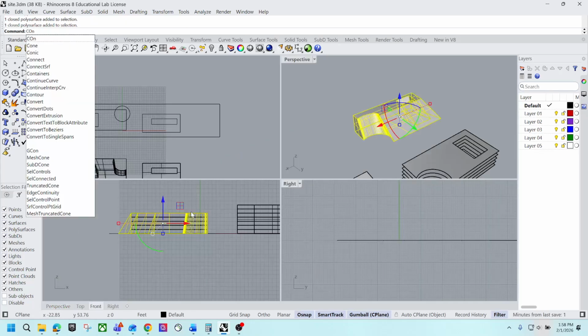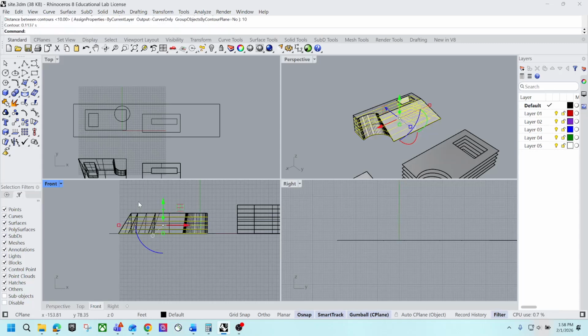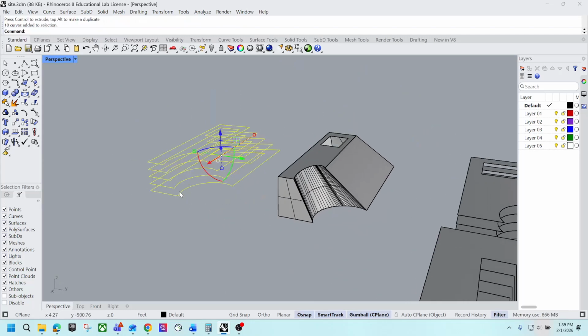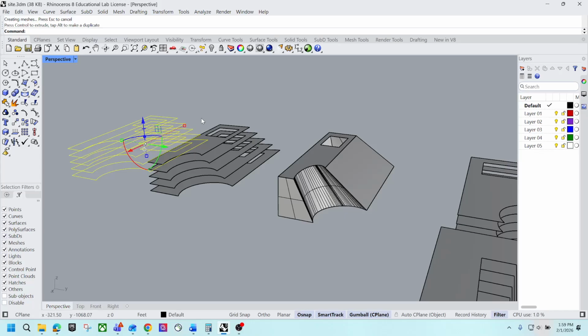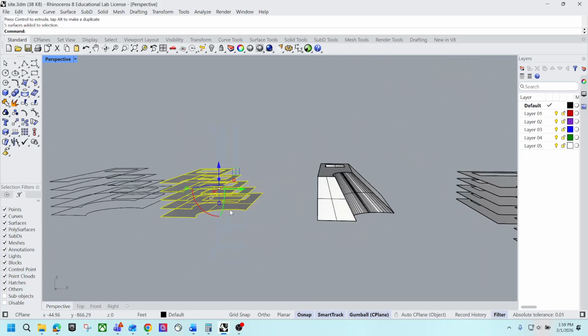This will be similar to what we have done before. Pick a point at the base, pick the z-axis, give 10 feet, right? So you're basically cutting this into contours. Once I cut the contours, I will do exactly the same command, planar surf, right? So I have each of these floor plans, which are different. This will be enough to calculate area. You can type area and calculate the total construction square footage.